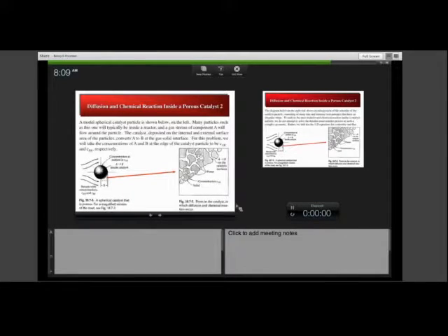And so you see again this coupling of the solution to a microscopic problem to a macroscopic problem in order to predict the performance of a macroscopic device. I showed you that in detail with the Stefan tube where we solved for the concentration profile of gas in the gas phase of the tube, and then used that to predict how rapidly the weight of liquid in that tube would change with time.